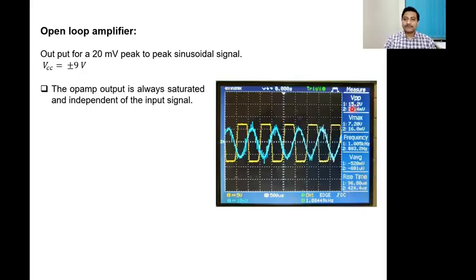Now, this is the oscilloscope that you will be using, and we can make some quantitative estimates by looking at these waveforms. First of all, the screen is graduated into a grid. Horizontally, it represents the time, and vertically, it's the voltage amplitude. Each division, or each block, represents a unit of time, which is shown here: 500 microseconds.